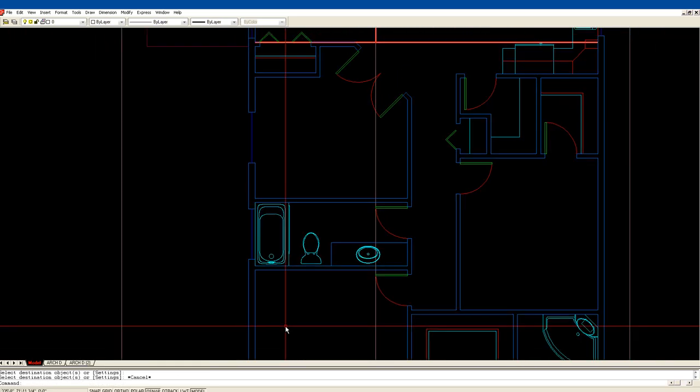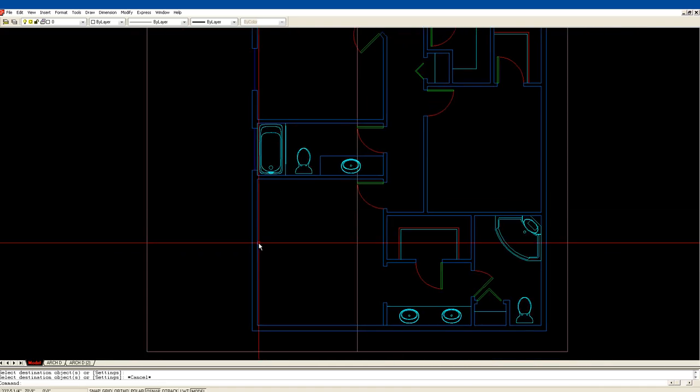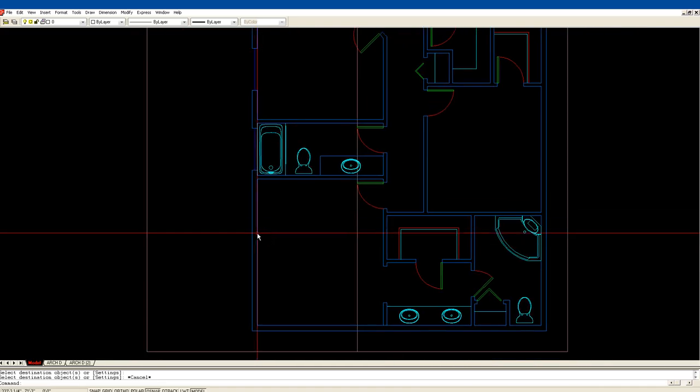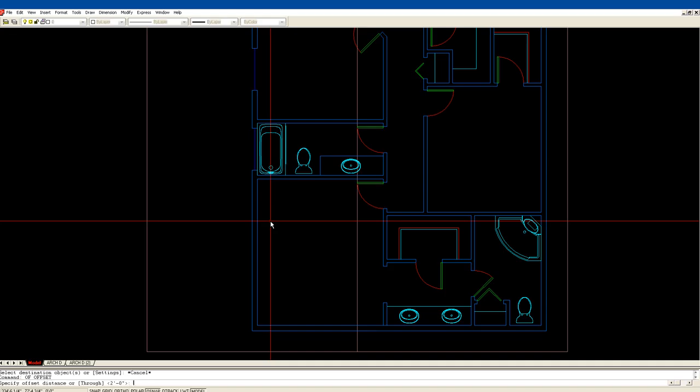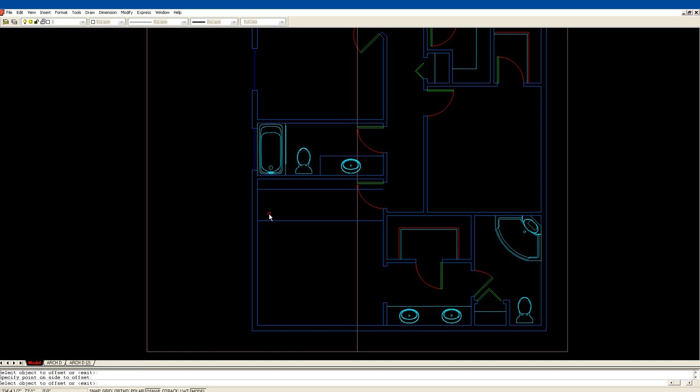Okay, this one, he actually wrote sizes for the master bedroom. They've put some thought into it, and they want 3 feet wide by 5 feet high, and they want them either end. You can see they're going to put their bed in the middle. So I'm just going to offset 12 inches, and then offset 36 for a 3 foot window, and offset 12 and 36.